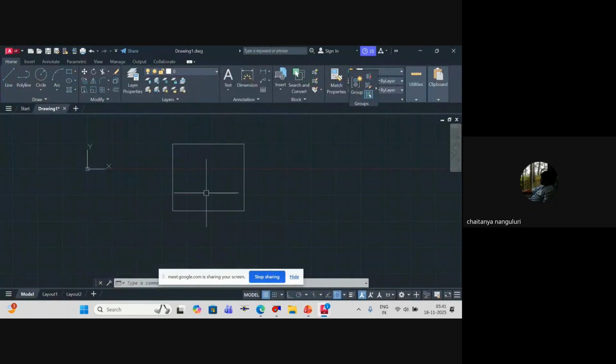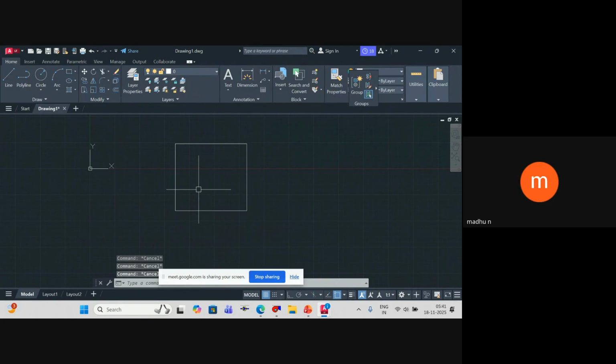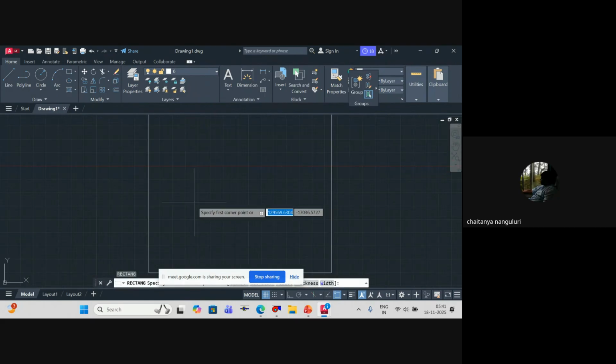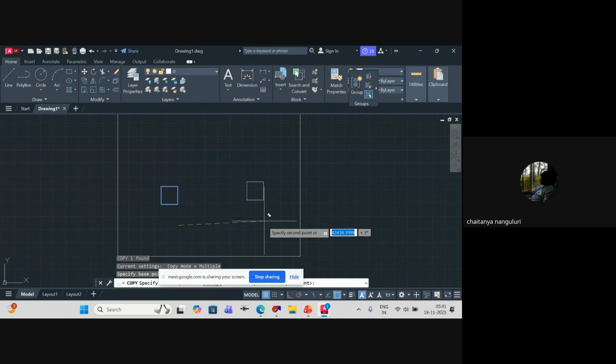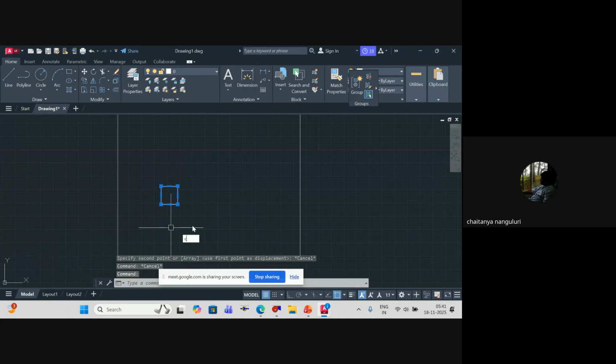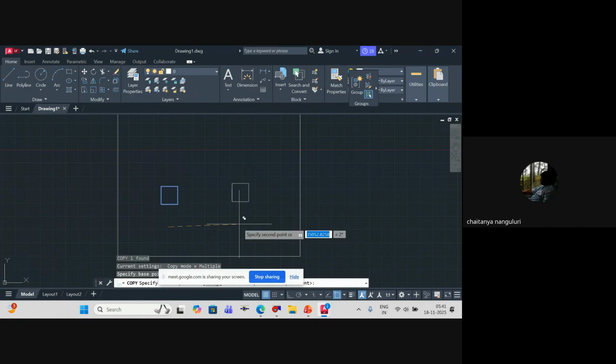So 7,200 square meters, and I have to make it into 3,000 each. Don't you think I'll require at least three compartments? Yes, we need three compartments. Definitely, you might get something like this. When you have a much bigger building, you'll have lifts for sure, mostly. You might have some kind of lifts.